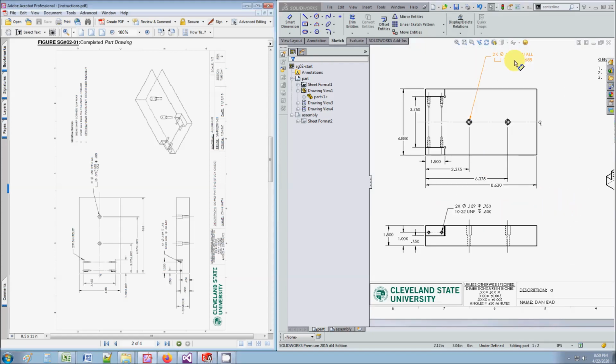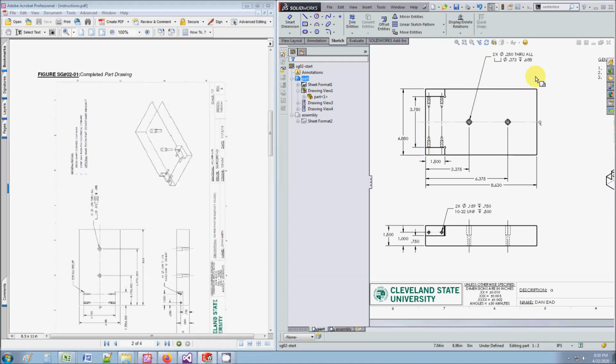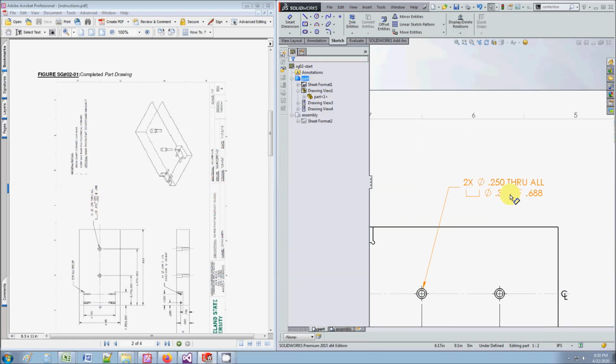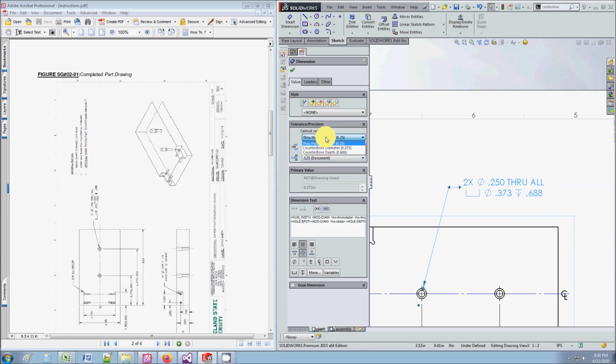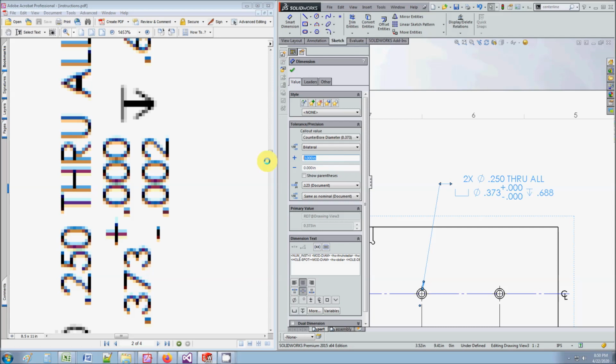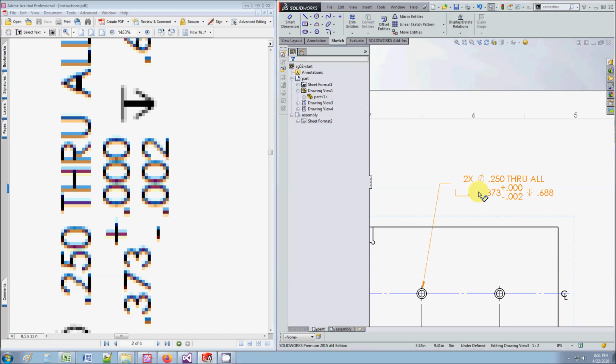What I'm going to do now is worry about the tolerancing and some of the minor details. So here you can see there's a tolerancing on the head diameter. You gotta look at the counterbore diameter, and you can see that it's a bilateral. Let's take a look. Plus 0, minus 0.2. So plus 0, I'm sorry, 0 and minus 0.02. Okay? So that's important. All these tolerances are important.